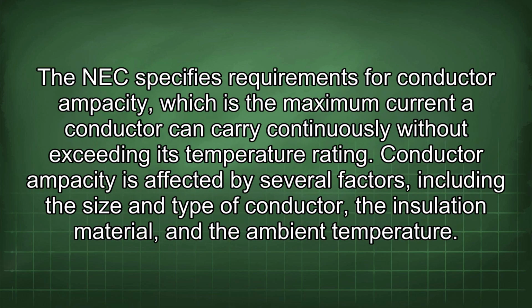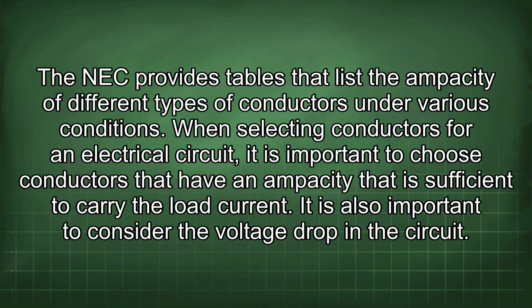The NEC specifies requirements for conductor ampacity, which is the maximum current a conductor can carry continuously without exceeding its temperature rating. Conductor ampacity is affected by several factors, including the size and type of conductor, the insulation material, and the ambient temperature. The NEC provides tables that list the ampacity of different types of conductors under various conditions. When selecting conductors for an electrical circuit, it is important to choose conductors that have an ampacity that is sufficient to carry the load current.